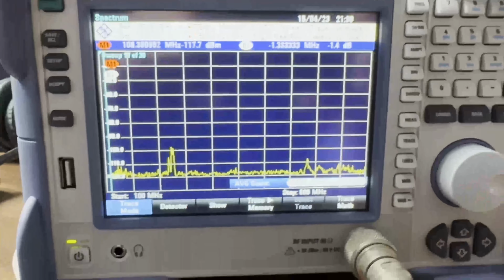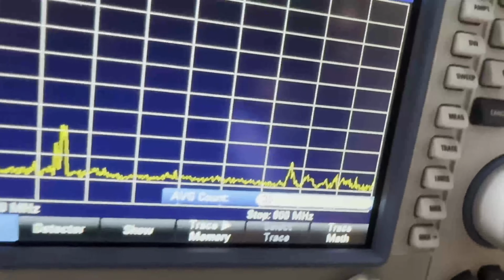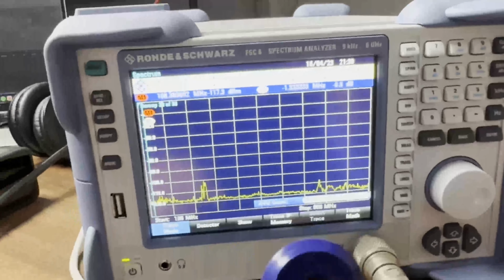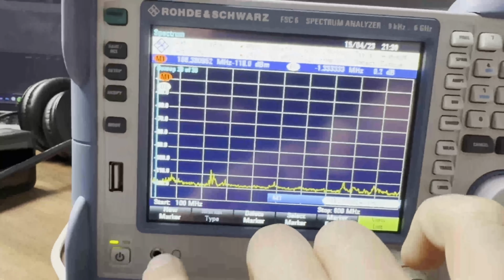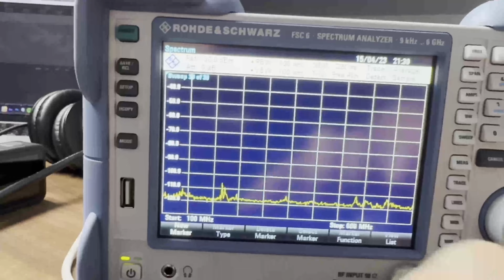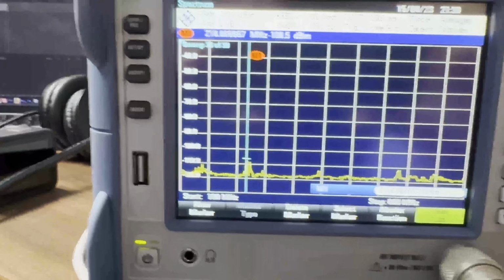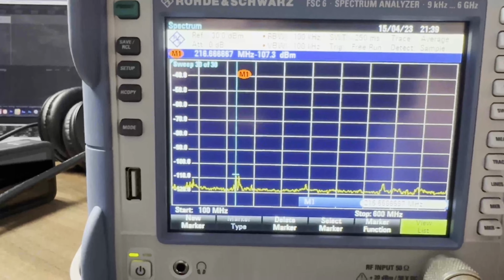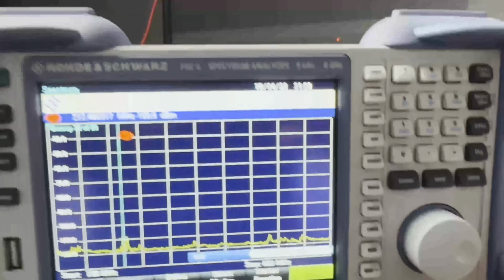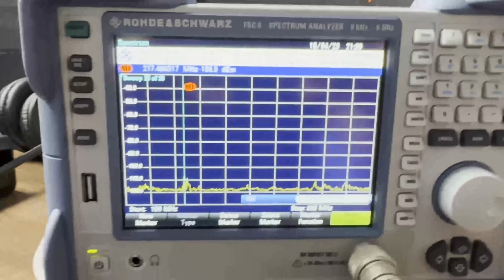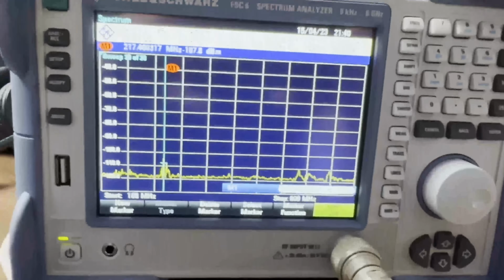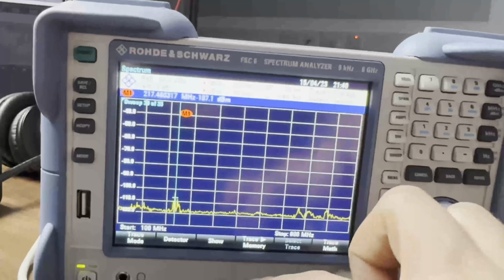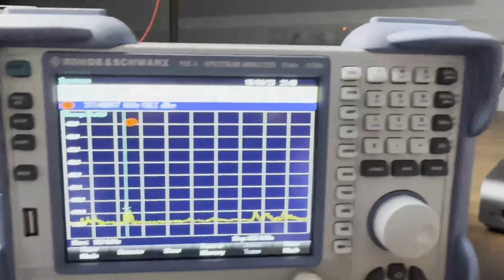Okay. So we're back on our default screen with this near-field probe, which is still the magnetic near-field probe that I've been using. I'm not completely sure why I'm receiving some spike here, but let's just delete all and add a new marker. And so that's a spike at 217 megahertz. That seems to be caused by the environment here. So this is just something we need to note, and we can do that by saving that as a trace memory. So now we can look at the actual board.